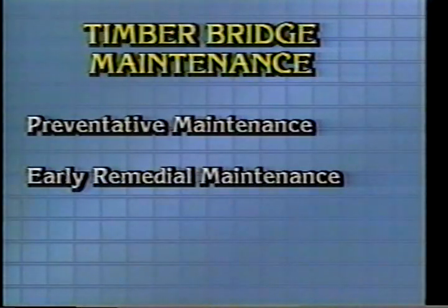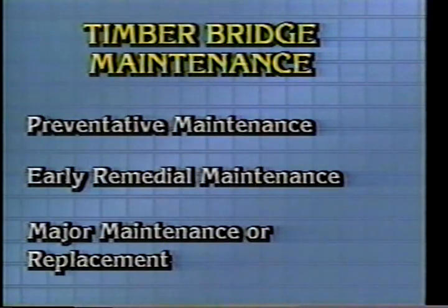And then the third category is major maintenance, major rehabilitation or replacement. Unfortunately, most timber bridge maintenance is ignored until it reaches this stage. In many cases, replacement of most of the timber members is necessary if it goes to this stage. In summary, wood is good if timber bridges are properly designed, constructed, and most important, properly maintained.